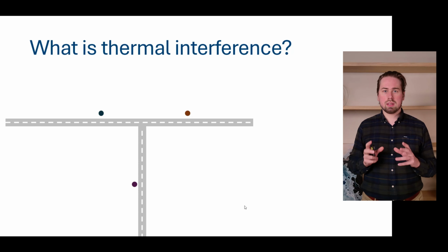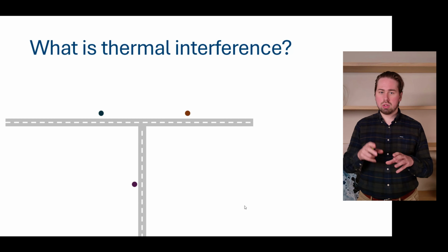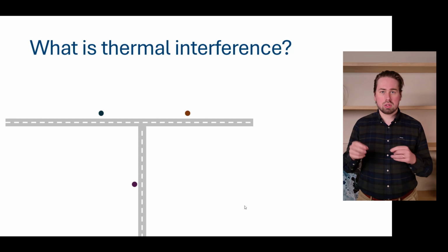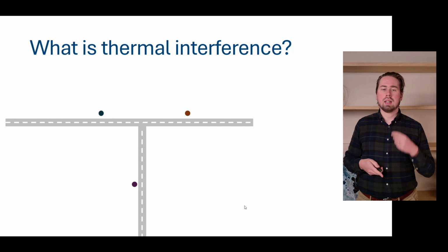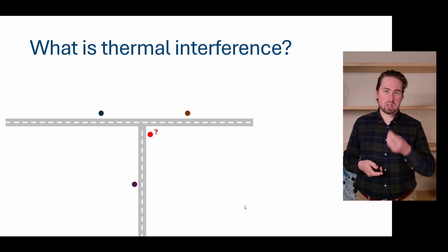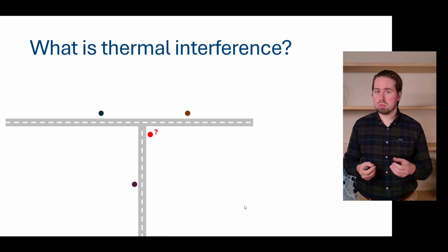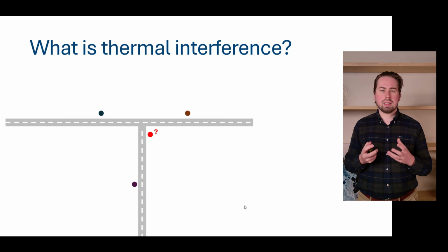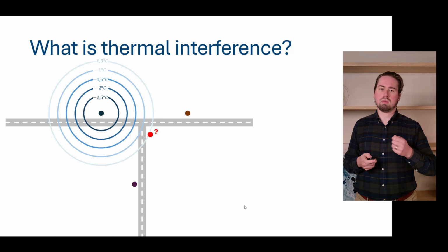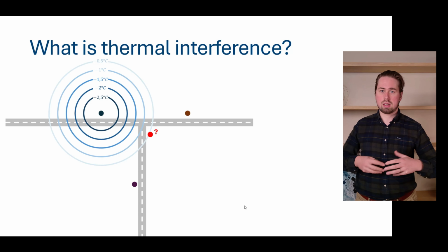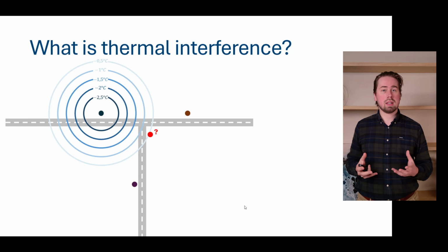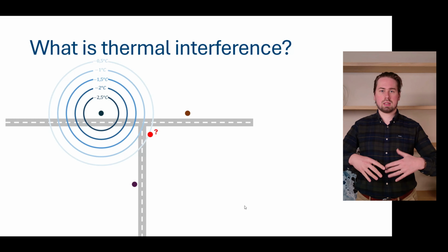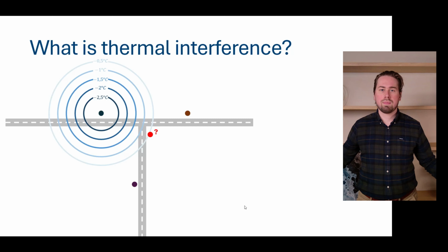To recap, what's interference? Imagine you have a district with a couple of geothermal systems already installed. And you ask yourself the question, okay, if I install a geothermal borehole myself, a bore field perhaps, how should I design it? Because every bore field, every borehole has a certain imbalance, probably. And this means that year after year, the ground will cool down, and this effect will also spread under the ground to our neighbors.